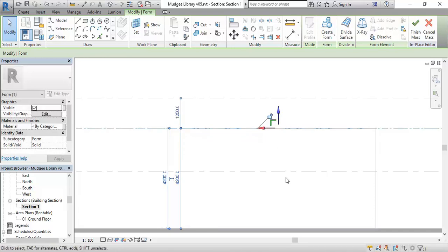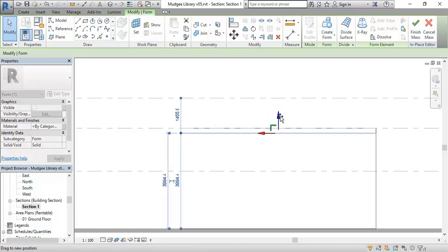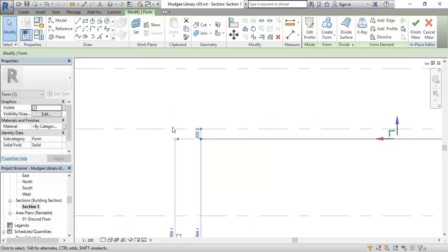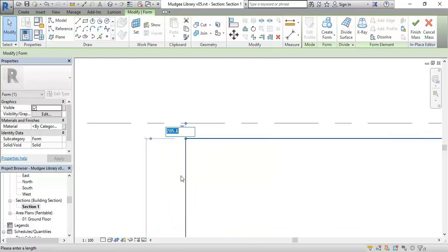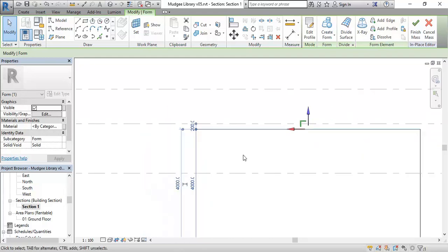That will probably be okay for analysis drawings. If you want to, you could leave a gap for your floor. If you're thinking you might use this for modelling, then you could bring this down and then you'll get a dimension to the level. And you can type in a set out there, so maybe 200 or something, to allow for the floor thickness.